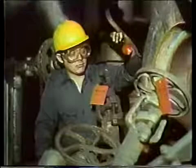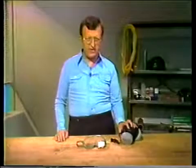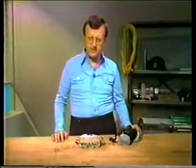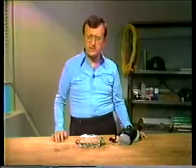Eye protection is important because of the possibility of the chemical solution splashing into your eyes. Most chemical cleaning solutions have acid in them that can cause irritation. Whenever acid is being used, clean water should be nearby so you can wash your eyes or skin in case of an accident. Some chemical solutions give off ammonia vapor. If you work with these kinds, you should use filter masks and eye protection. Filters like this will remove the ammonia vapor from the air and let you breathe safely. If strong ammonia vapors are inhaled, hospital treatment may be required.